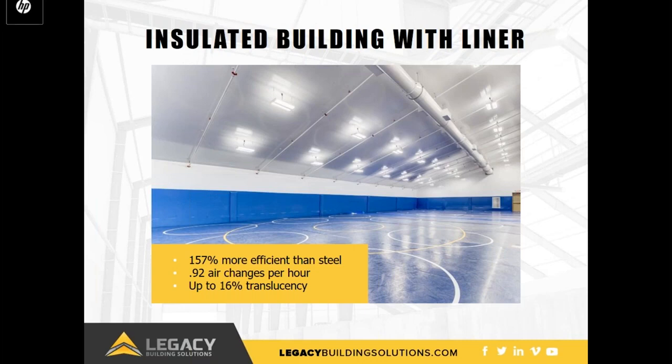Architectural fabric can have some degree of translucency. The Exotech PVC that Legacy uses has up to 16% translucency. On a sunny day, this provides enough light to safely work inside the building. Natural light spreads through the building, preventing shadowy corners or dim areas that are common inside steel-clad buildings. This natural light can also mean a significant reduction in the number of light fixtures that must be installed and maintained throughout the building.